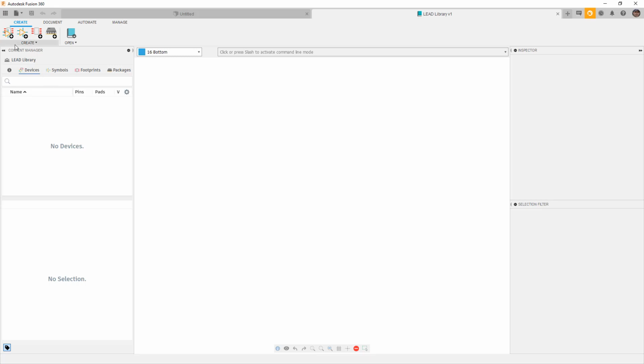So I'm going to start by creating a new device. My new device name is just going to be a 1206 chip resistor. Now you'll notice when you start this that everything is going to be capital and everything will be next to the character before it. There are no spaces. So if you want to add spaces, you'll need to use things like underscores. So in my case, if I want to have space, I can go ahead and add it. And you notice here I forgot an S, resistor.